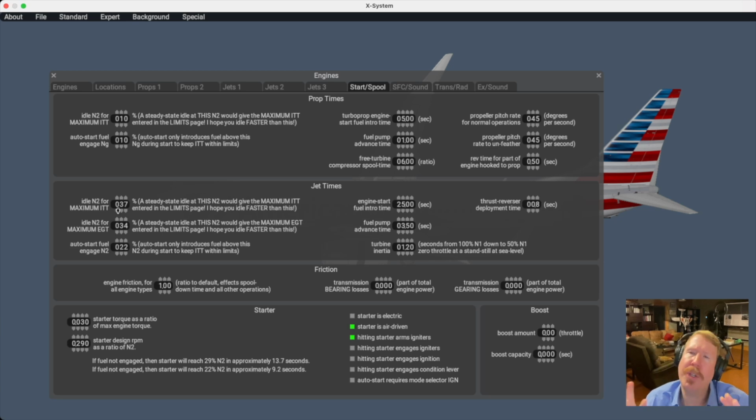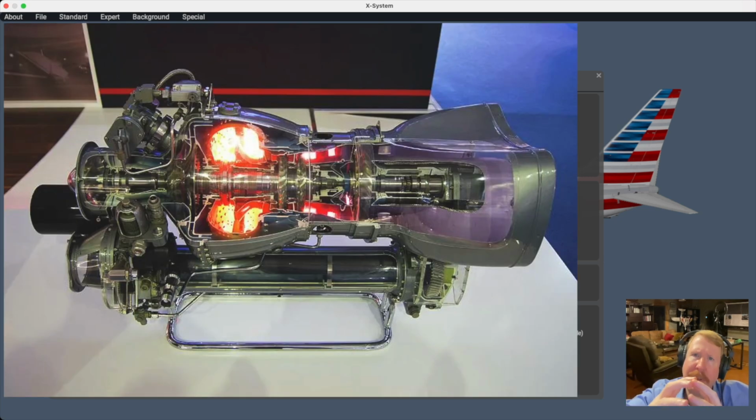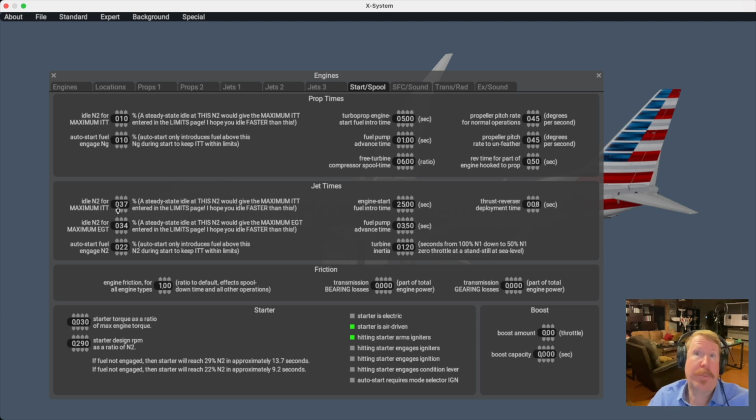All right, remember the way all these turbines work. They're all the same. Turboprops, jets are all the same. There is a combustion in the middle of the engine that is so hot, it will melt the engine if it ever touches the engine wall. Literally, all the time a jet is running, there is a temperature in that flame that would melt the engine if it ever touched the engine wall. And the only reason jet engines and turboprop engines, for that matter, are not destroyed every single time you fly them, even once, is that there's so much RPM pumping so much air through the system that an insulating wall of air exists between the combustion and the engine wall, and that's literally what protects the engine.